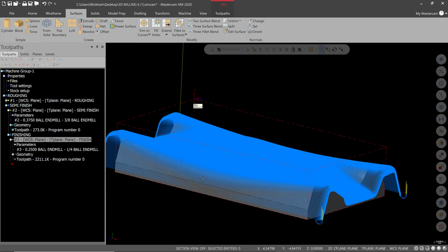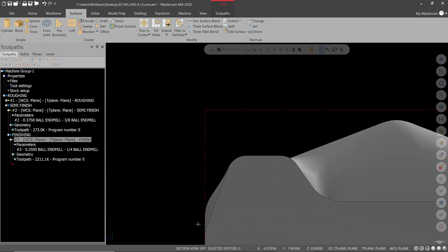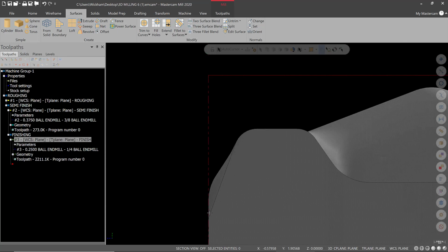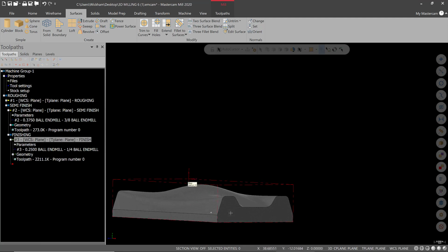Another way to minimize this is to change the direction of the toolpath. You can go this way instead of long ways, and that will minimize it as well. It'll look close. It's not going to fix it, but it does help a little bit. So that's that. Again, don't worry about the red. I know people are going to panic there. Don't worry about it. That's just a flat wall that exists. If you take a look at this and you look at the right view, you'll see right where that red line is, it's pretty much flat. So that is already gone. That is why it's not really contacting there, because it doesn't need to be machined. That's why it goes up and over like that. So don't worry about it. That's fine for this. I'm not going to have you machine all the way around. I'm not worried about it for this example.